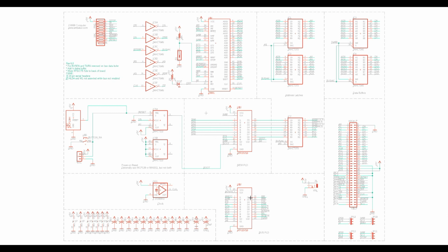And then down here, we have another which handles the bus. It looks at the various states of the CPU, these ST0 through 3 bits, and some other lines, and it will generate your memory read, write, IO read, write, strobe, stuff like that, as well as some chip selects for some of the onboard peripherals.